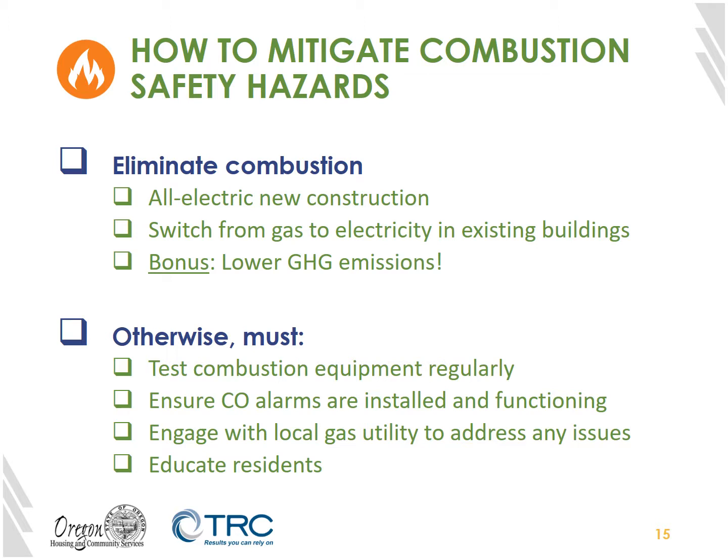So if not, we need to ensure that we test combustion equipment regularly, ensure our CO alarms are installed and functioning, engage with the local gas utility to address any issues that we identify, and finally educate residents about what they can do to ensure that their combustion equipment is operating safely.